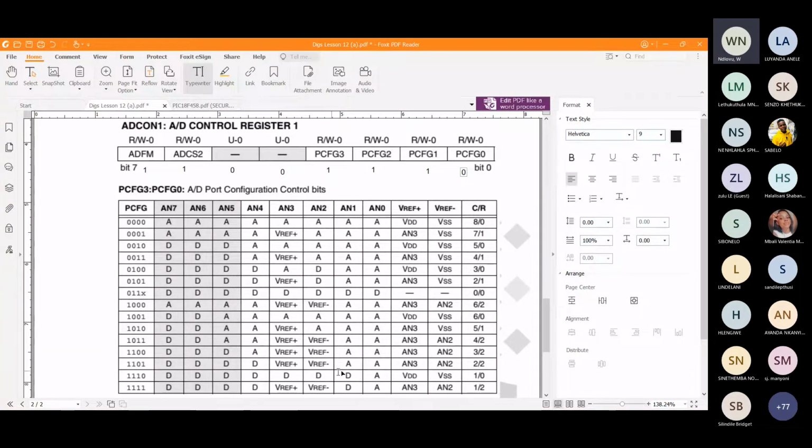So this combination, guys, shows you what you can get if you make any combination. But this combination depends on what you want to do and your specification. If the specification says nothing about the external reference voltage, then you assume you are using VDD. But if we are given the positive ref, then you choose the channel that will have your positive ref.